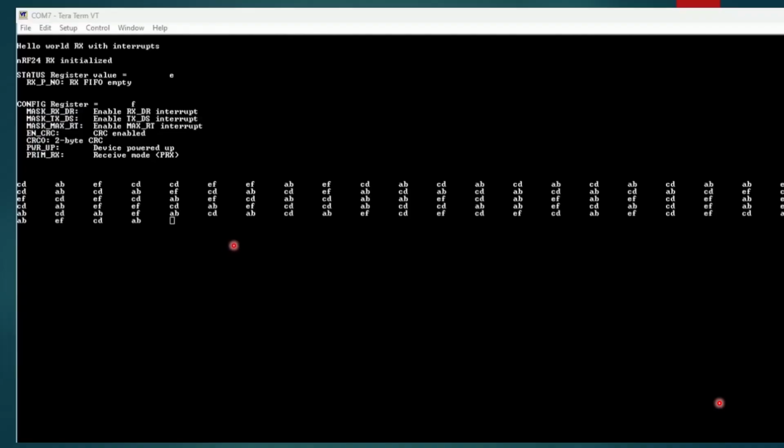So I think you get the picture that we are dropping messages. We tried using polling, we tried interrupts, but still we're dropping some messages, and that may be okay, because the messages are coming every 100 milliseconds. That's a lot of messages. So we're dropping some, but we may be okay. If we want to turn on an LED, we may want to send the message 4 times, and we'll eventually get it.